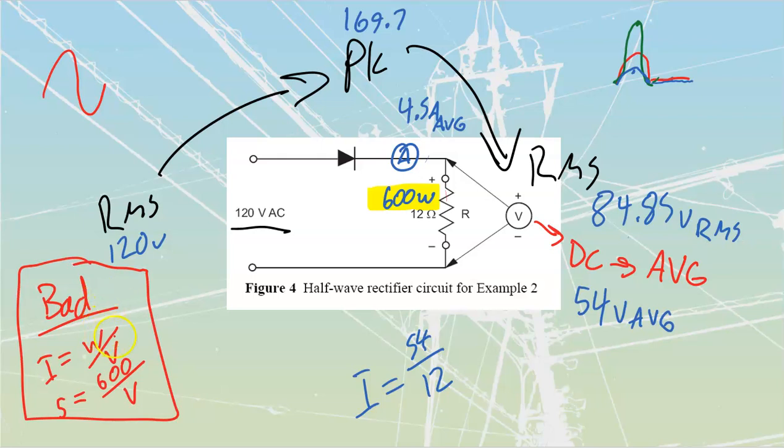How does this formula work? This formula works off of the fact that it's going to be an RMS value of voltage that's happening for both cycles. When we rectify, when we're blocking here, is there any current that is flowing? Absolutely not. So that means that this current that we would have over here would not actually be like that, because this formula on this side would be us assuming that we're going to get the complete waveform being passed through, and therefore we're going to have some current on this side, and some current on that side. That's not what's happening. Right now, we're getting current only on this alternation, and we're getting nothing happening through there.